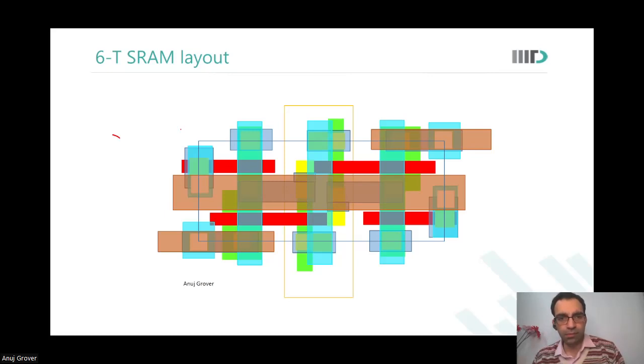For VDD, no, sir. We have just taken the substrate connection. So for VDD, the connection comes in the strap region. Okay. So where do I provide that strap region? I said after 64 rows we will give a break into the memory array, and it is there that we would have the connection for VDD.